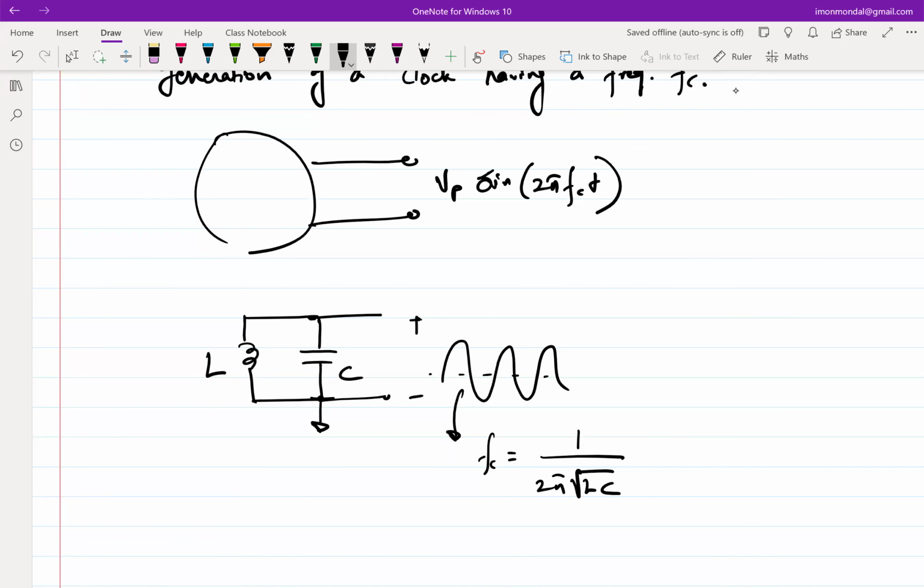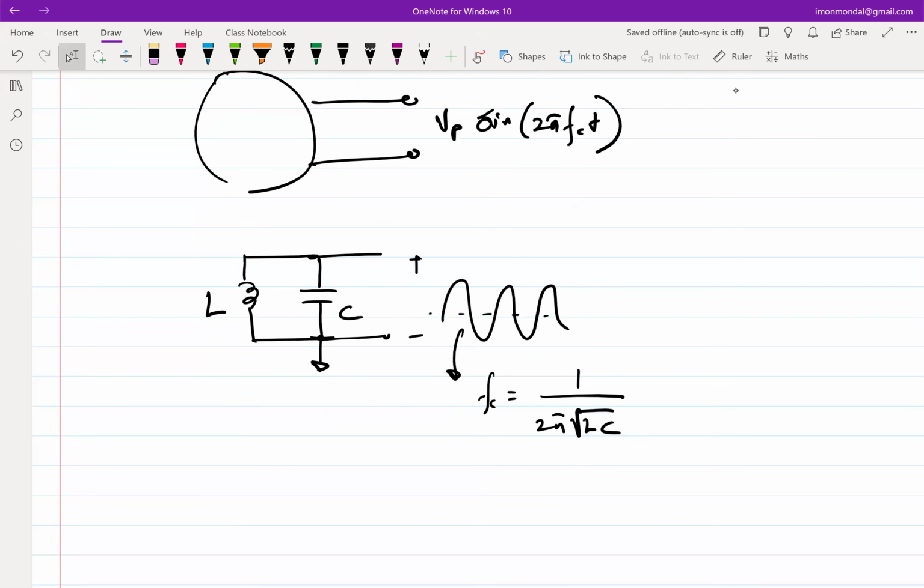If only. The issue is you do not have an ideal LC oscillator. You always have loss, so some R associated with it. The genesis of that R can be a leaky or lossy capacitor, or even the loss through an inductor. You can as well put some R in series with the inductor, and that also will model a loss. But just to keep things simple, I'm putting R in parallel. The effect will be the same for all, but the details will vary.